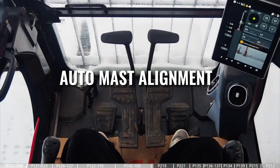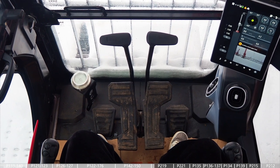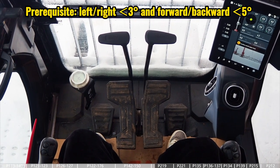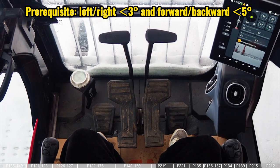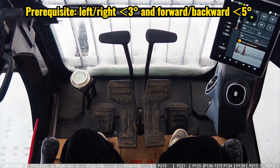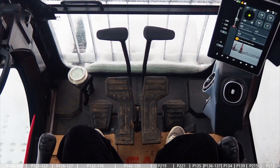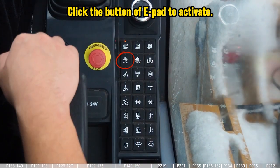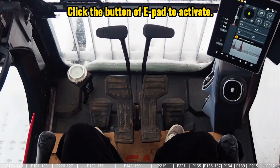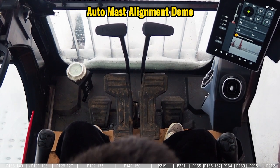Alright, in this video, we're going to talk about the auto mast alignment function. The requirement to activate this function is that at the left or right, the degree is less than 3 degrees. And for the forward and backward, it's less than 5 degrees. And what we need to do is just click this button once, and the machine will start to align by itself automatically. So now, firstly, let's incline the mast a little bit.